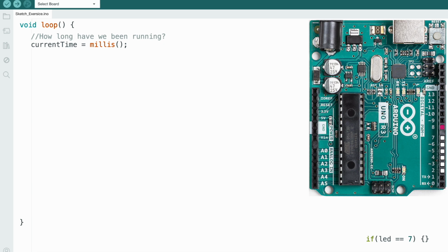You can see here it goes into the current time, which is the unsigned long. And from there, the very first thing that we're going to do is say, hey, is the current time minus the previous time. And the first iteration of this loop, previous time is set to 0. So current time minus previous time is current time. If it's greater than that interval, which was in our case 600,000, which it's not, then you would fall into this iteration. So every 10 minutes, essentially, you would fall into this conditional.